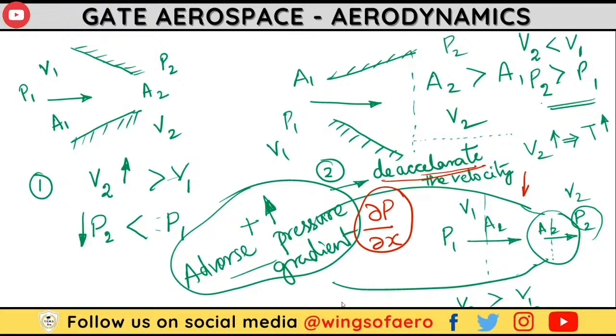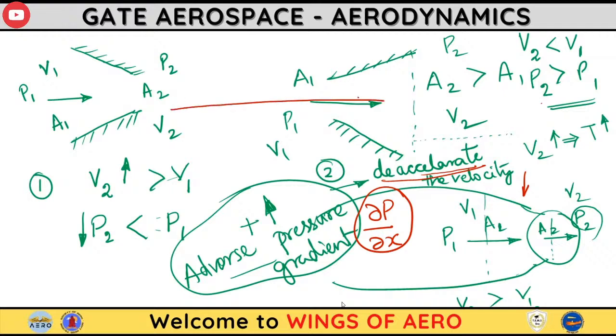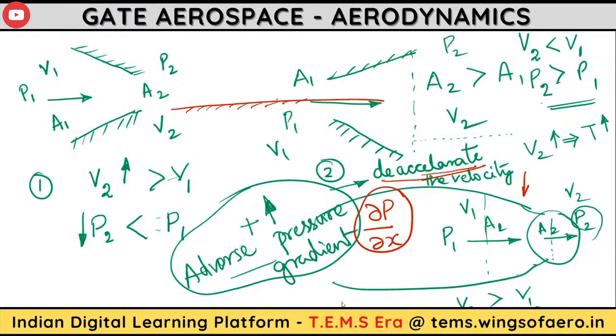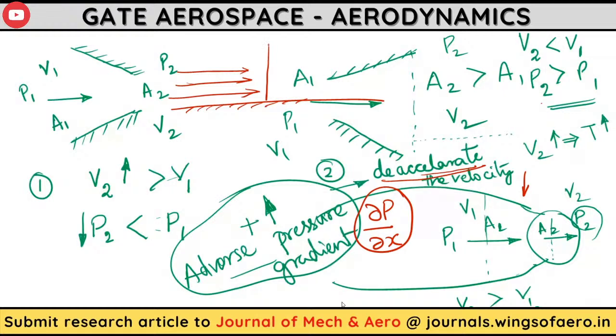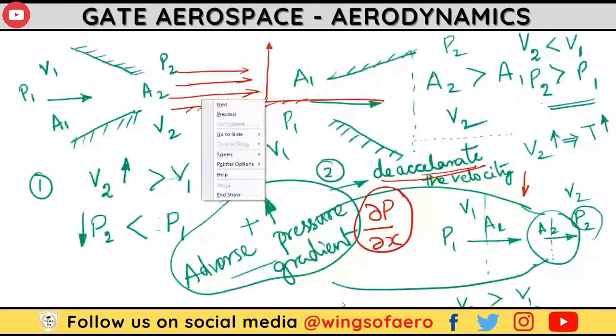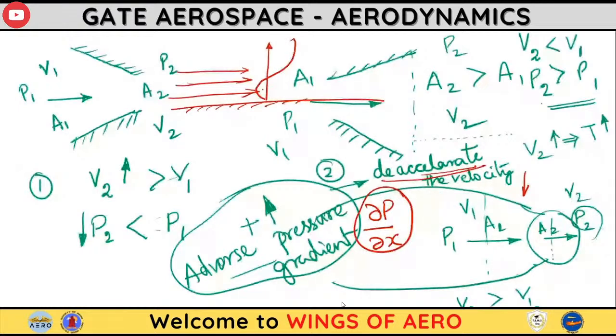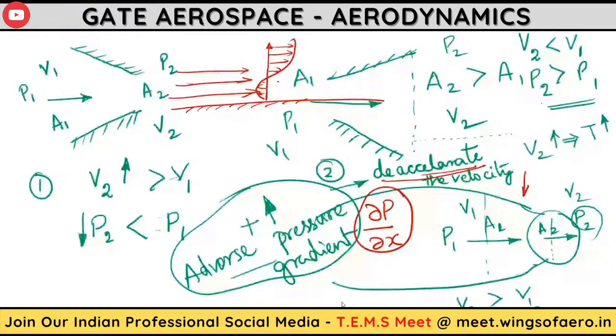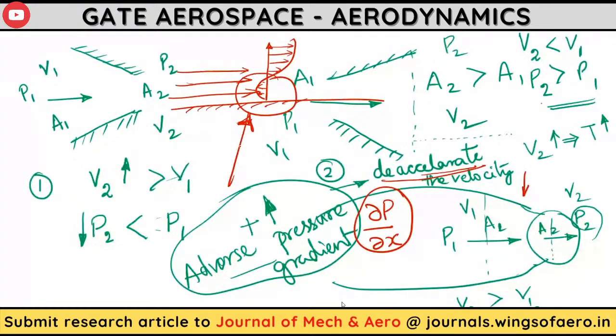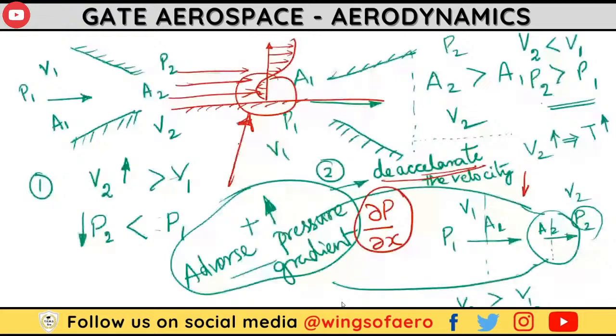The same thing happens in the boundary layer. Suppose you have a surface, and flow is moving over the surface. Suddenly, due to the deceleration, if I take this one as a reference, it starts to move along a reverse path, in an opposite direction. Or we can say flow separation. This leads to an increase in flow separation. So this phenomenon leads to an adverse pressure gradient. When there is a flow separation, that finally leads to an adverse pressure gradient.